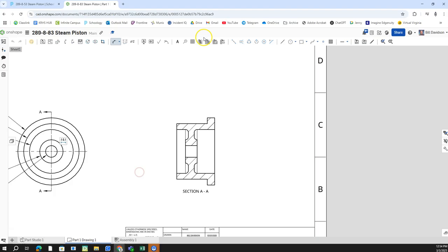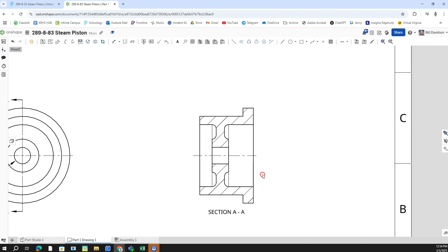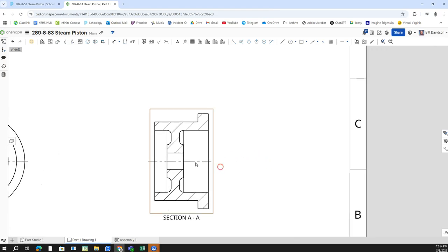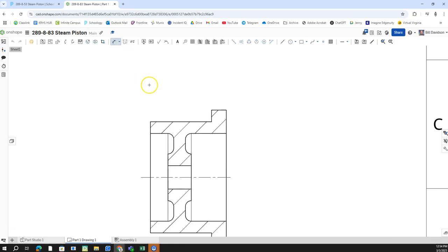And then this one, we'll go in here and we're going to add center lines between that and this, and that's fine right there. I'll just click this one and I'm going to just drag that out so it goes through the whole thing. All right, so that tells us there's center lines. And then I'm going to dimension some things here from the top. I will dimension that line to that line and make sure that that's 0.5. And that's clean. You can do it that way.